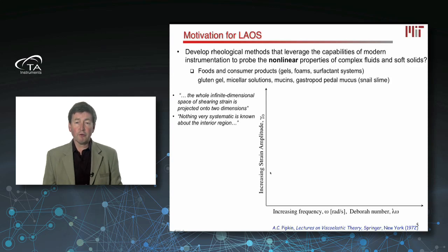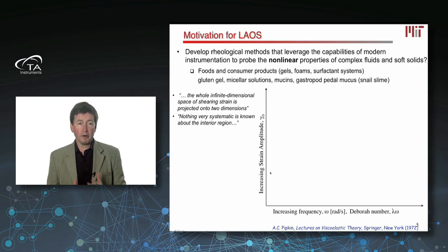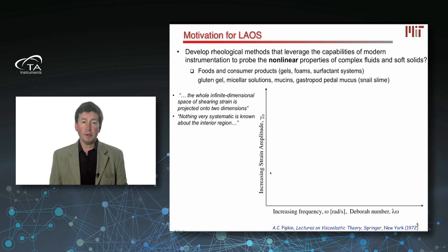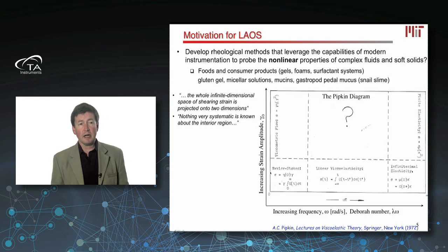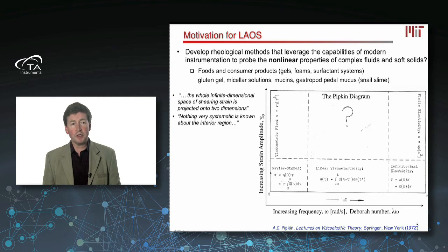Typically, you have to do that at a small strain amplitude. So on the vertical axis here, what I'm showing you is the idea that we might also quantify the strain amplitude of the response, and that's an input parameter typically to an experimental test program. Pipkin sketched out what is known about this space, so here's his original sketch from his lectures.